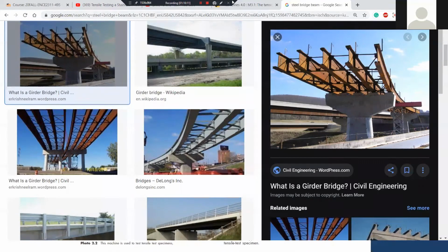It does. With corrosion, you reduce the cross-sectional area, and also the chemical composition of the steel is being changed. So if you change a certain characteristic of the material, as a result, the tensile strength or compression strength of this material will change.